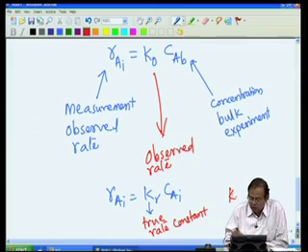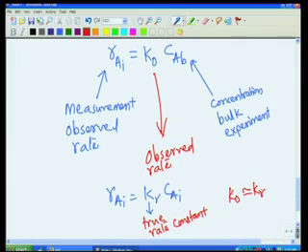If K naught is very similar to Kr, that is when mass transfer resistance is negligible, then we are measuring the true kinetic rate constant. But if mass transfer resistance is very high, where K naught is almost equal to Kg, the mass transfer coefficient, what we will be observing is the mass transfer coefficient rather than the kinetic rate constant.